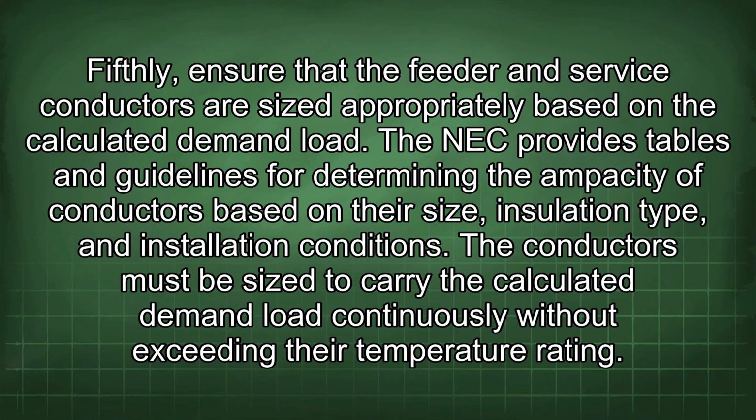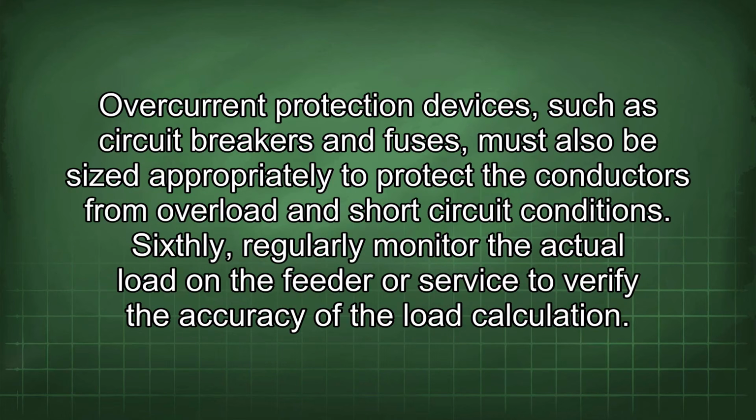Fifthly, ensure that the feeder and service conductors are sized appropriately based on the calculated demand load. The NEC provides tables and guidelines for determining the ampacity of conductors based on their size, insulation type, and installation conditions. The conductors must be sized to carry the calculated demand load continuously without exceeding their temperature rating. Overcurrent protection devices, such as circuit breakers and fuses, must also be sized appropriately to protect the conductors from overload and short-circuit conditions.